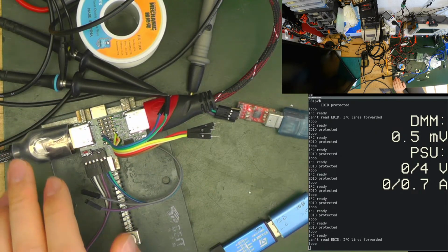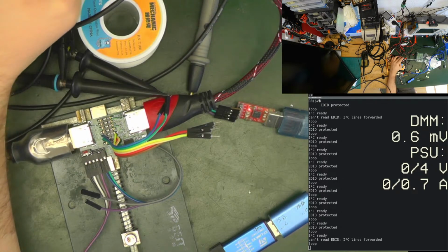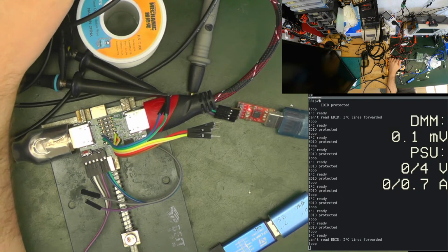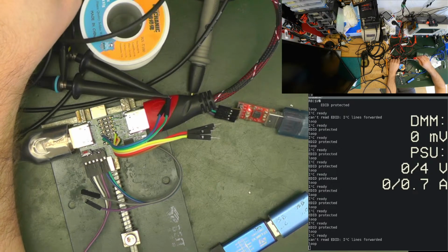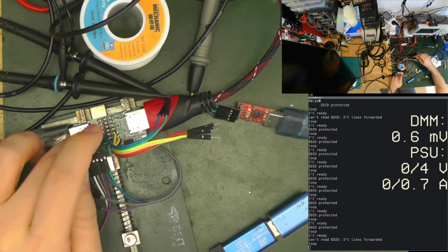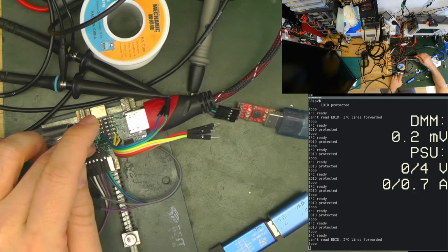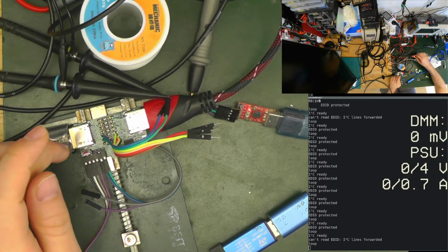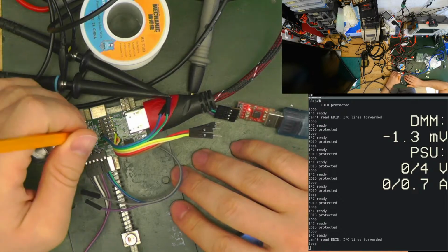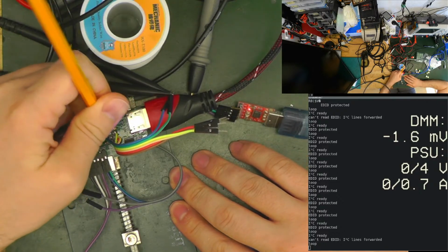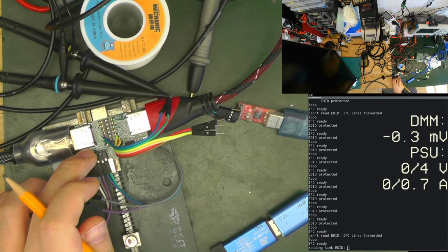I2C lanes forwarded. Okay, it detected that they are forwarded. That's good. But actually, why? It detected that they are forwarded because the other one was pulling it up. That's good. If only one side is there, it detects that it's forwarded, and because it's forwarded, it can't read the things. So let's try again.